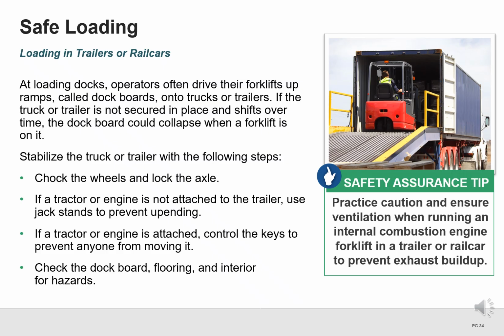When loading trailers or rail cars, forklifts are often driven up ramps, known as dock boards. If the trailer is not properly secured and shifts, the dock board can collapse while the forklift is on it. Before entering, always stabilize the trailer.